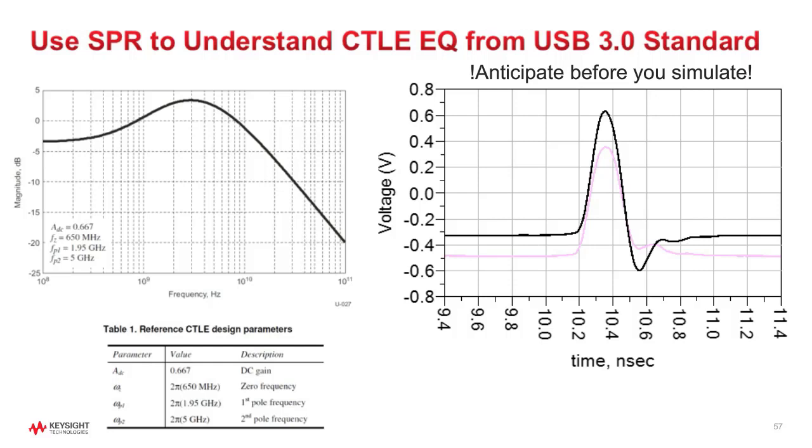So if you look closely between the time 10.2 nanoseconds to 10.5, the width is the same. But what's coming afterwards is crucial. It's taking away that leakage ISI. So that's how it's helping the jitter. Not from shrinking the pulse width, but from taking away the leakage.